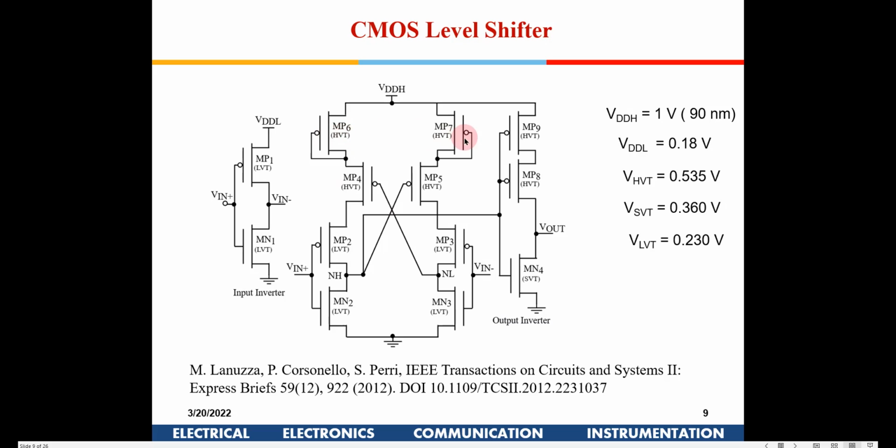So the purpose of these two diode connected PMOS is just to scale down the VDD here, right? Now if you see this particular output, for logic 1 it will be around 0.4. Now from 0.8, this logic level has come to around 0.45. And we use a normal inverter here to again get back to the 1 volt system, right? So it is like one set of inverters where I have a Vin of 0.18, then I get around 0.45 here, and then I get the full voltage here.